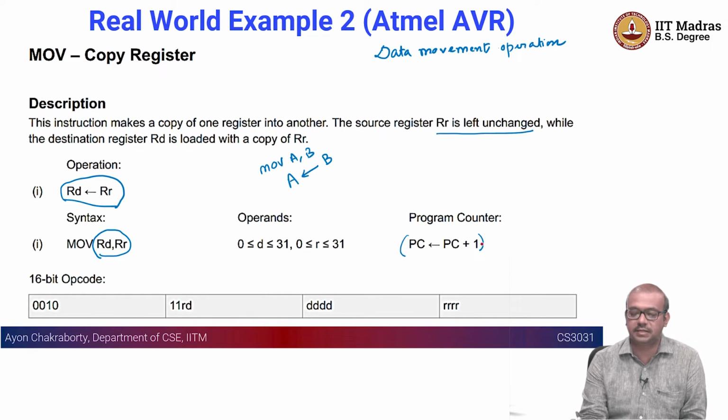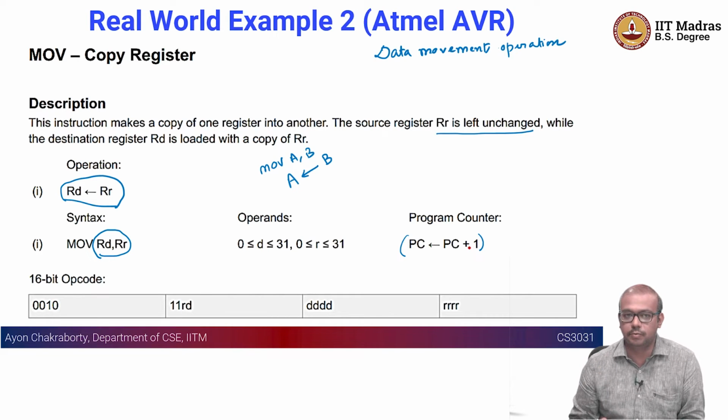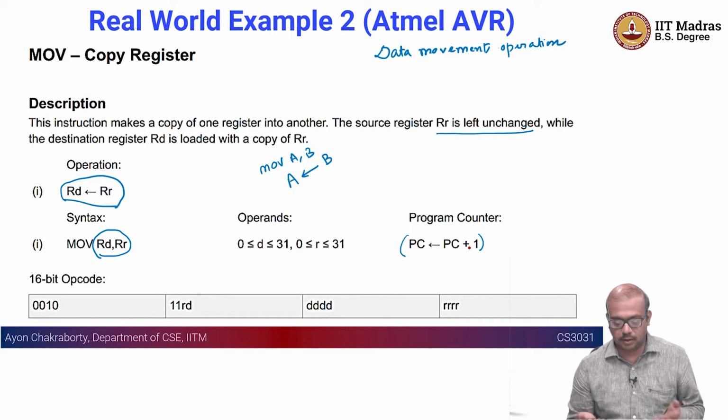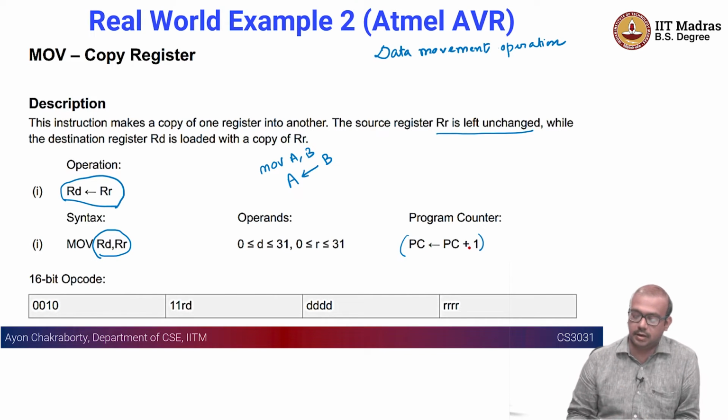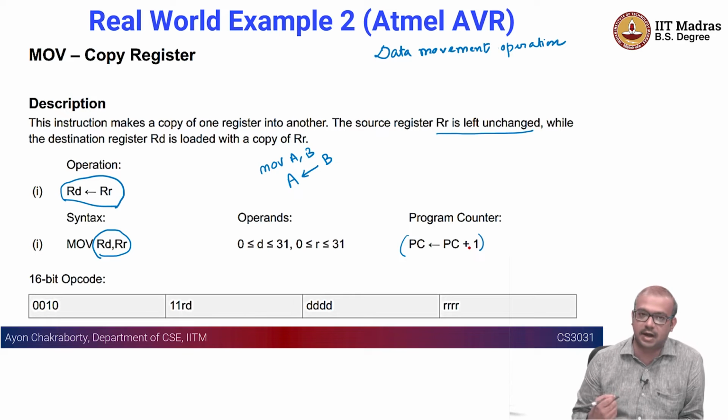In our case, this program counter is pointing to an instruction, and that instruction could be having, let's say, 16 bits, right? And it basically goes to the next location in the memory. Okay, so it could increment the program counter by 1 here. The value is that next address.